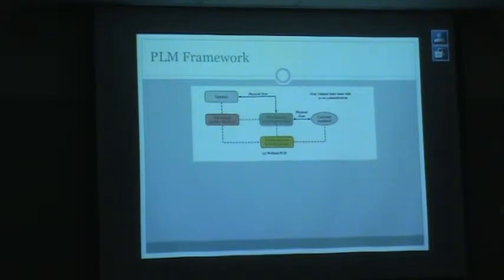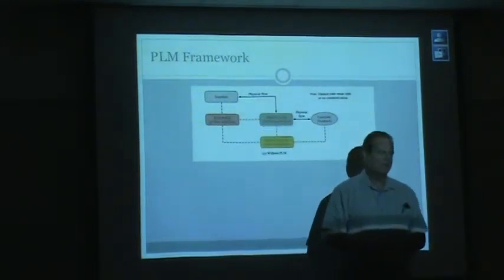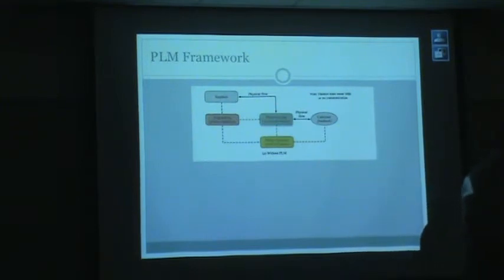Okay, your textbook also shows this little diagram, and I apologize that it's not real clear on the overhead, but it's intended to show you how a company without PLM is organized, and these dashed lines that show up, quite a few of them, are areas in which it's kind of an over-the-wall treatment. If you want to get something to your supplier and they don't have a PLM environment and you don't have a PLM environment, what you typically do is produce a set of drawings and what?